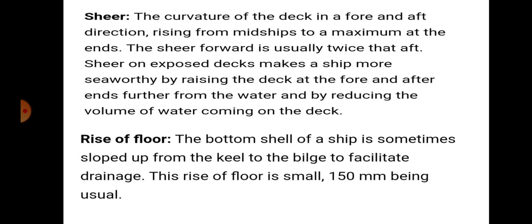Shear is the curvature of the deck in the fore and aft direction, rising from midship to a maximum at the ends. Shear forward is usually twice that aft. Shear on the exposed deck makes the ship more seaworthy.